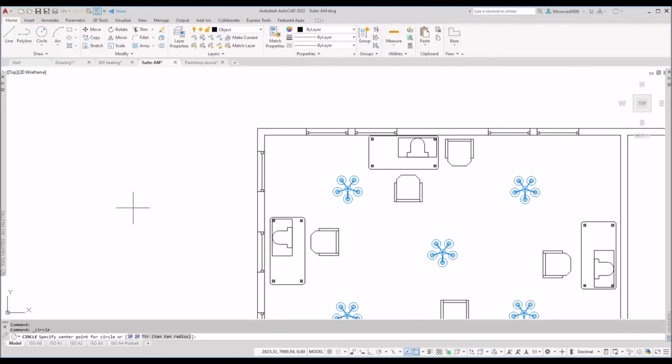At this point, I turn on tracking. It's not object snap tracking. This is tracking with the letters TK. So Tango Kilo. And the command line now says, where is your first tracking point? Well, my first tracking point is this corner here. Click and bring my cursor down the screen. I can see it's going up the screen, so up the screen there, look, I'm going to come down the screen and type in 200. And now I come across the screen by 100.